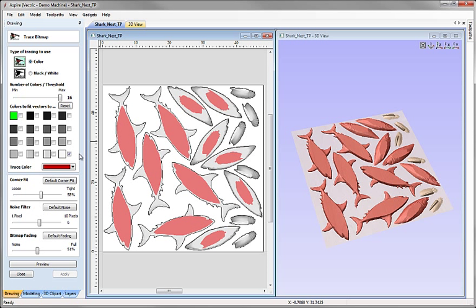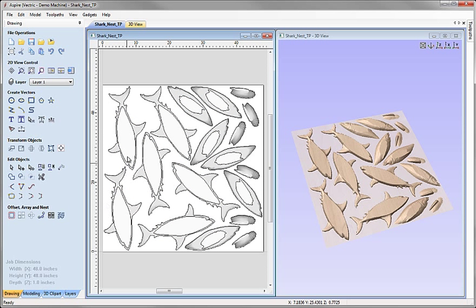The white represents the highest area of the part and therefore basically is that top boundary of the slice. So with that selected, we can adjust the parameters in here. I'm going for around middle for loose to tight fit and around middle for the noise filter, and then go ahead and hit preview. The red color is showing me the area that that vector is going to be fitted to. If I'm happy with that, then we can just hit apply and close, and there we've got our set of vectors that represent the top edge of each slice.